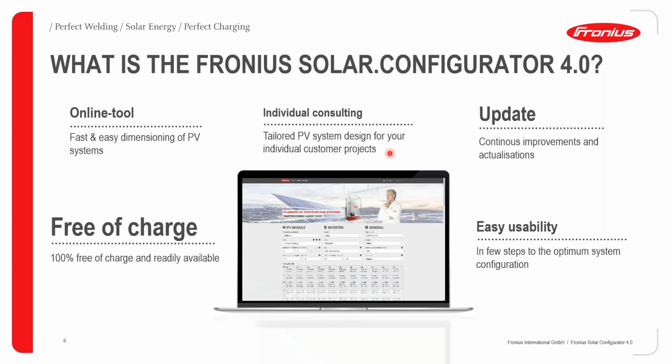It provides a form of individual consulting. The Fronius Solar.configurator is extremely good to make sure that you do the correct string planning for your Fronius inverter. Just note that you can only use this platform with a Fronius inverter. You can't use the Fronius Solar.configurator with another manufacturer's inverter.